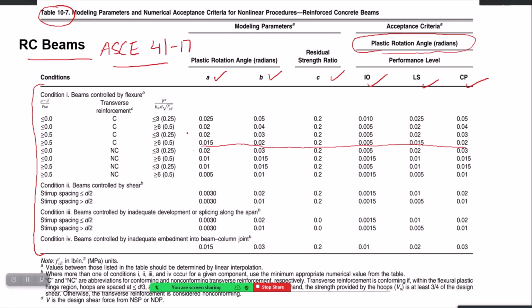So once you have these 6 numbers, you can define your moment versus rotation behavior, and obviously it will now be a rigid plastic behavior. So it directly starts from the yield point, goes to the ultimate point, and then comes down and just finishes at the end, maybe at some residual value, and then goes down.